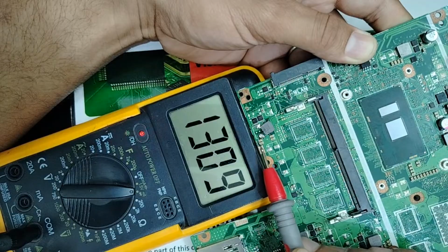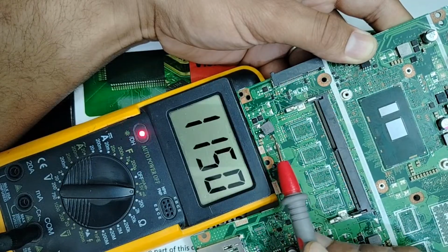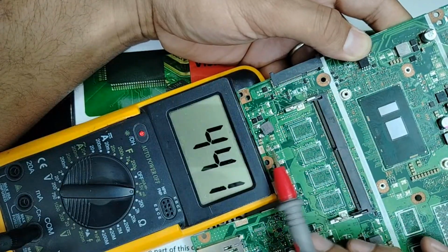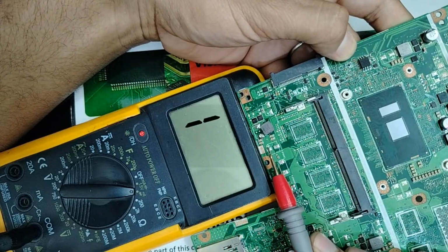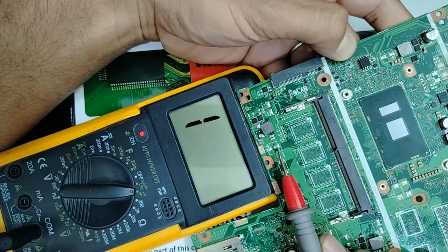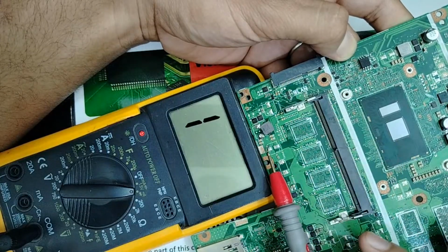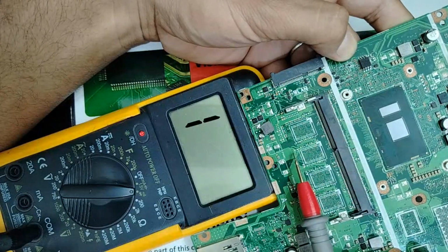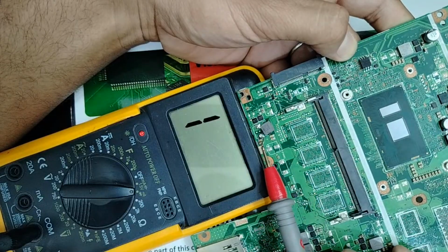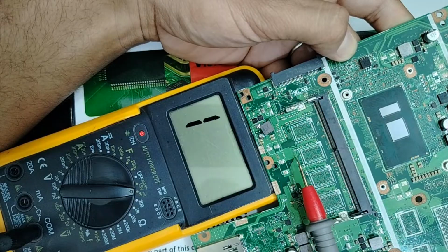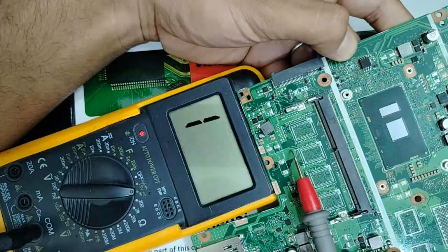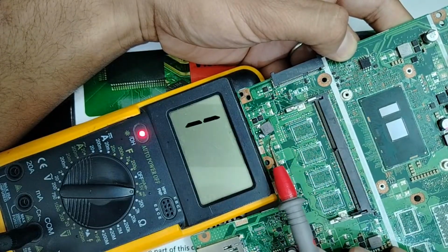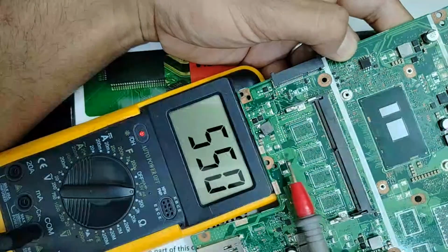So it could be these ceramic capacitors here. This one or this one or this one or this one, etc. But, my friends, it could be these ceramic capacitors connected basically to this electrolytic capacitor, which is not connected from the manufacturer. If we follow this part here, we have these dots. Do you see these dots, my friends? These dots mean this part here is connected to 1, 2, 3, 4, 5 parts in the motherboard. It means it could be that these ceramic capacitors are shorted, or the short could go here.